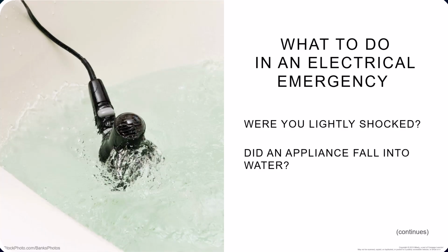If the outlet is not GFI protected, go to the breaker box and flip off the current. If you are unsure which circuit controls that outlet, it's better to just shut off all of the power to everything while you fix the situation. And once the power is off, unplug the item and then restore the power. And you should never use an appliance that has been dropped into water.